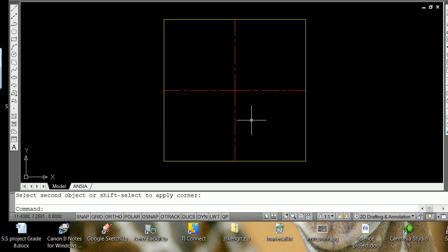This is going to be a little bit different from working with the draw commands. It is a modify command, so you select the thing first with a left click, then you left click over the spinny point, if you would, and you want to get used to then space barring through till you get to the command that you want. Again, you can right click, but you're going to rotate, C for copy, and you're going to turn it 80 degrees in a positive direction, and so you get that there. That establishes one of those lines, the 80 degrees off here to the left.